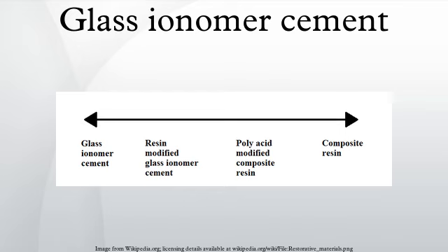The raw materials are fused to form a uniform glass by heating them to temperatures of 1100 degrees Celsius to 1500 degrees Celsius. The glass is ground into a powder having particles in the range of 15 to 50 micrometers. Typical percentages of the raw materials are: silica 41.9%, alumina 28.6%, aluminium fluoride 1.6%, calcium fluoride 15.7%, sodium fluoride 9.3%, aluminium phosphate 3.8%. GIC liquid.